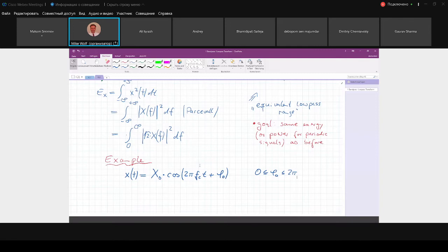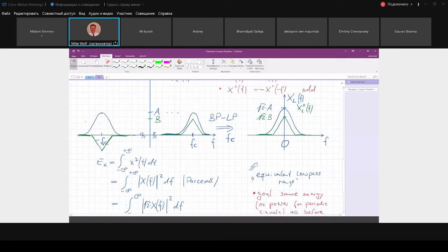But look, this is really important, and we can write this. Now, the real part of this spectrum is even, right? The imaginary part of this spectrum is odd. Look, in this example, the real part is still even, but look at the imaginary part of the spectrum, whose symmetry is still even. So this means the time domain signal in this exact example would be complex.